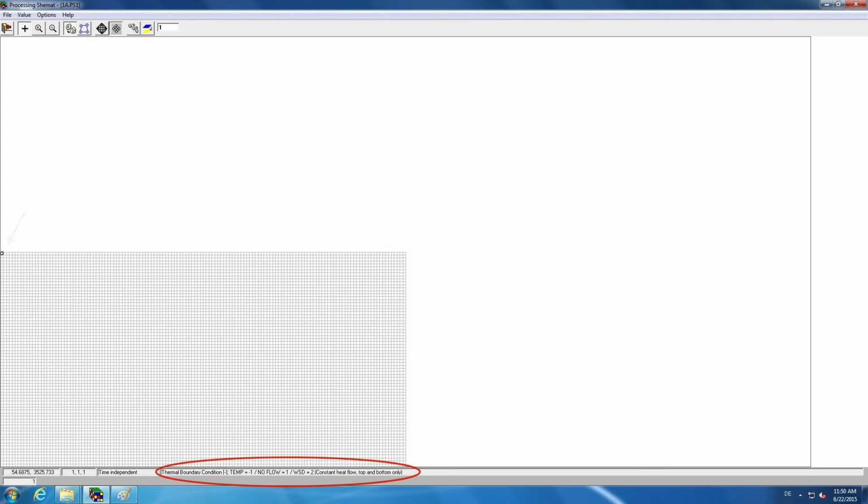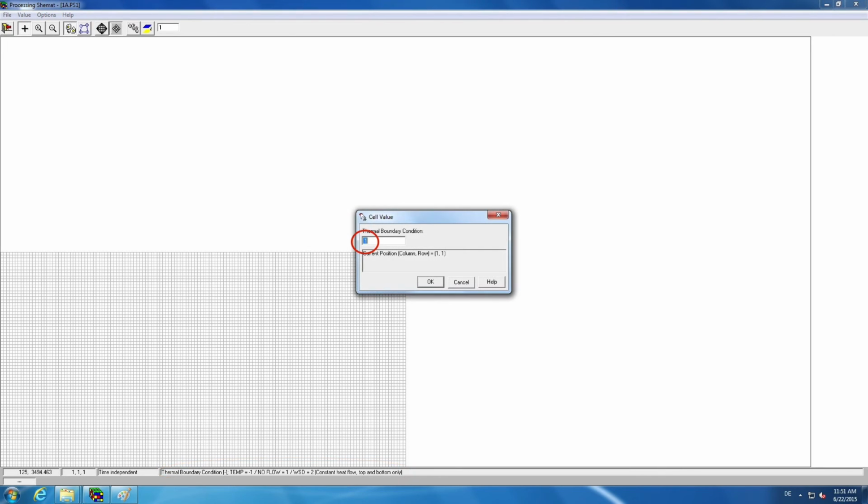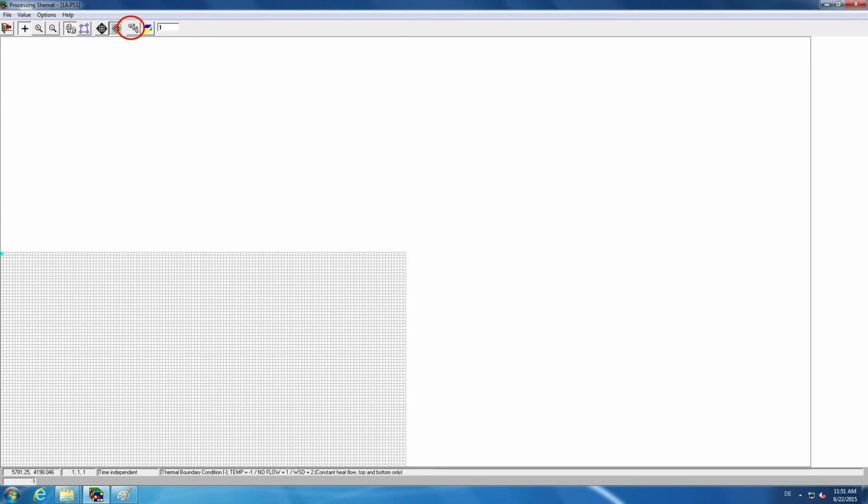of the grid. Now you need to assign code numbers to the boundaries for identifying the type of the desired boundary condition. The default setting for all grid points is 1, meaning no flow. For the top boundary, set this value to -1, meaning temp, as model 1A requires a constant temperature at its top boundary. Now switch on the duplication mode and move the cursor all the way to the right along the top boundary. Now, temperature of all nodes at the top boundary will be held constant at the initial temperature during the entire simulation.